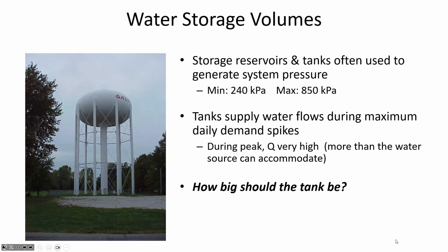But those plants aren't able to dial up and dial down their production flows with as much variability as you're likely to see in a 24-hour period. I mean, if there's more demand, they can definitely increase their treatment capacity, but it would be tough for a plant to have a huge range in flows.